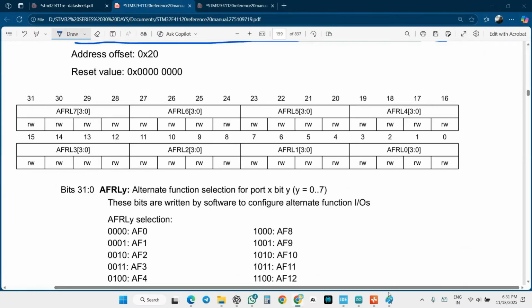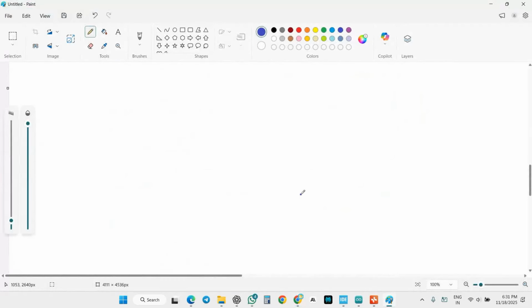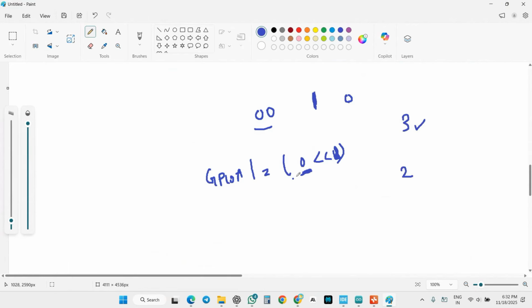You can see this one, guys. You cannot set 0 0 anywhere. Just think about it. This is one of the registers, GPIOA, and when a 0 is left shifted up to 8, it is not going to be set. 0 is not going to be set. Always 1 or some other data only gets set. If you set 3, yes, it gets set. If you set 2, it gets set. But 0 does not make any sense because it is a reset value. It is just considered as a reset, so 0 cannot be set.